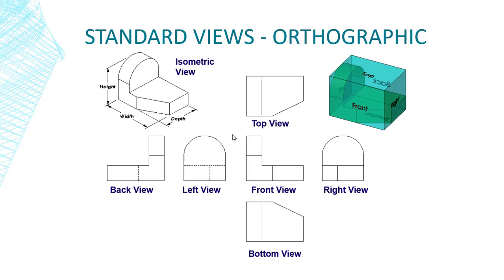But as a general practice, you select the front view as the side that has most of the important features. For example, in this case, I have this height, width, and there's this cut as well. So this is the face. When you look from that side, this is a face that has most of the detail. So as a general practice, we use that as a front view. But anyway, the whole goal of the drawing is capturing all the details from different angles, so that when you give it to a manufacturer, they can produce that for you. Okay, so now we just discussed the introduction.